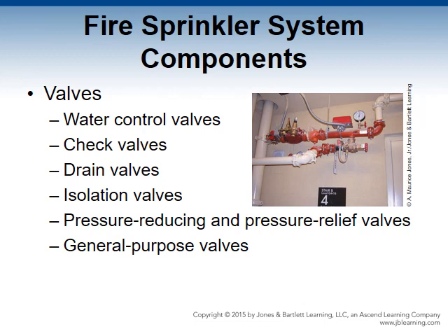One or more valves may be necessary depending on the size of the building. They should be installed in locations that are clearly accessible or marked for emergency personnel to have ready access to the valve. All water control valves must be of the indicating type. These valves should have a permanent metal or rigid plastic weatherproof sign identifying the area the valve services. All must be able to handle 175 psi or carry an appropriate rating for an anticipated pressure above 175 psi.